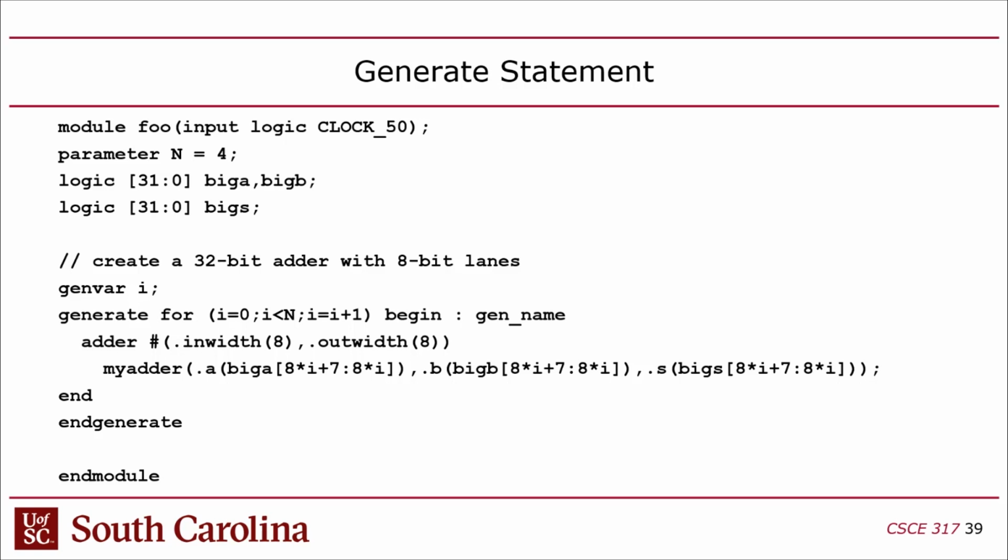Okay, I have a question. This generator code is looking less like hardware description language and more like a programming language that generates more HDL. Yeah, this is basically it. Is it actually doing like a Tcl script inside the simulator? No, it's generated internally in the compiler, but yeah, it is very similar to what a Tcl script would do, because you don't need a generate statement. You could just, as a programmer, copy and paste. But the problem with that is you would have to copy and paste it a fixed number of times. It would be difficult to change n. The nice thing about this is n is adjustable.